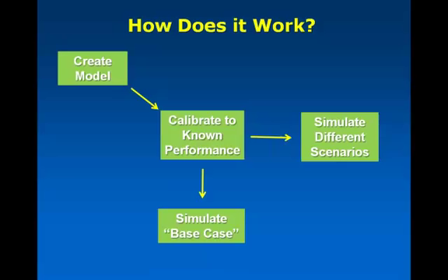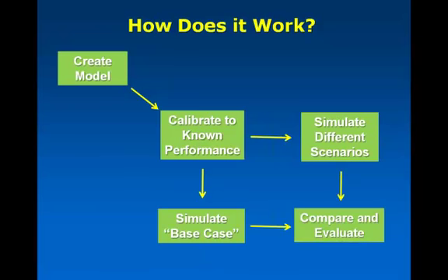So once that's done and you've established what your base case is, then you simulate your different scenarios, and that could be anything depending on what your question is that you're looking into. So you may be running at different SRT, you may run it under different operating procedures, try different influent, and whatever those questions are that you're asking of the model. And then once that's done, you compare those two things together to see what the difference is in that performance. So that's sort of modeling in a nutshell right there.